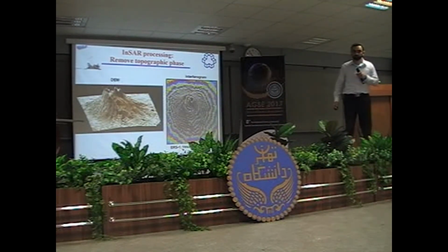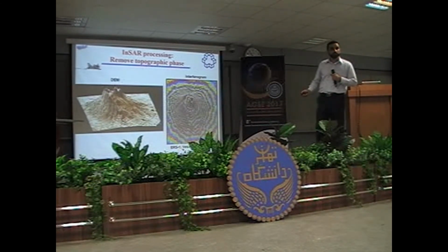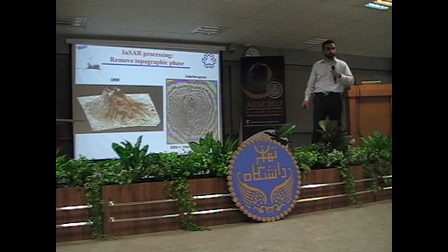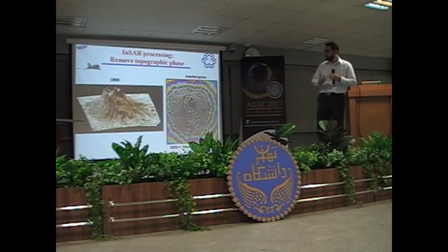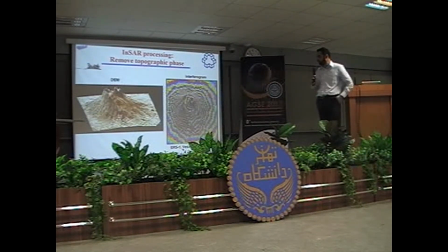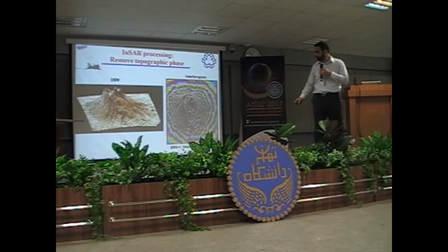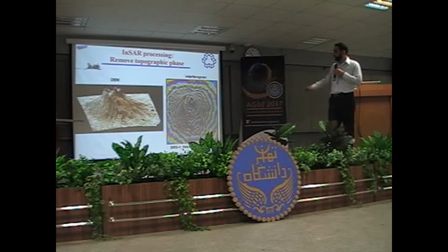How accurate is this digital elevation? Yeah, that's a good question. Is it possible for a flat plane? To calculate the DEM, you mean from a flat area? Yeah, you can generate the DEM for any kind of area. But the accuracy is different. Actually, I put one slide in the application part and give you some information about the accuracy of the DEM. But at this one, I can say for the SRTM case, the vertical accuracy is in the order of 10 meter. 10 meter, right.